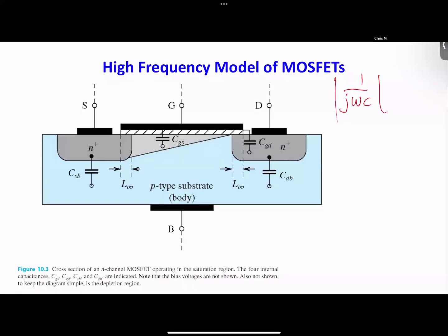Well, this is where we need to, that's why I want to review the small signal equivalent circuit. So now we need to get back to the small signal equivalent circuit, because for large signal, for DC, all these capacitors don't work because they're open. Who cares, right? For DC biasing, it's no problem. So only for small signal, it becomes more impactful. So therefore, we have to consider. So now we need to look at what is a small signal model.